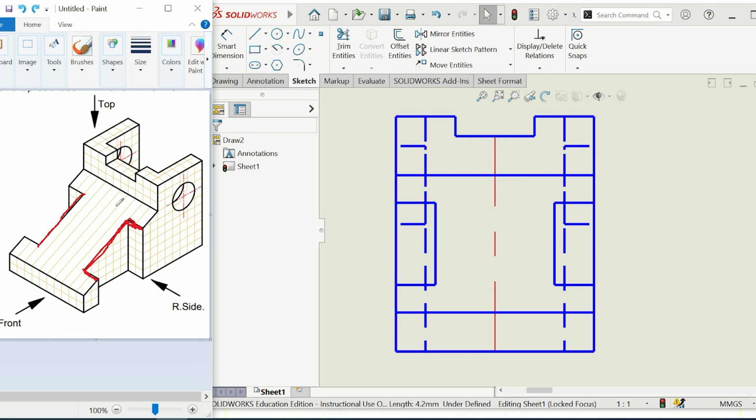Now, one more thing in the front view. As I told you earlier, I want you to focus on this edge. Looking from the front, it starts as visible, visible, visible, visible, visible till here. When you reach the height of this point here, then it goes to invisible or hidden here at the last section, meaning it becomes dashed here.